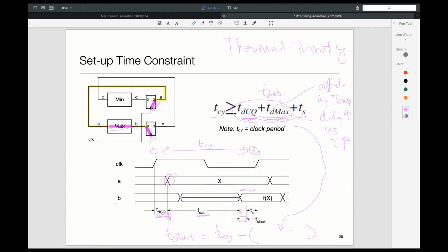So clock rate is proportional to clock frequency. Power consumption is proportional to clock frequency. And power dictates the thermal dissipation. If you're cooling at the same rate, but you're burning more power and not able to remove it, your removal rate is fixed but you're producing more power. So all that heat gets trapped, the temperature goes up. And as the temperature goes up, the delays go up and power consumption goes up. And that's when you enter into this vicious cycle.